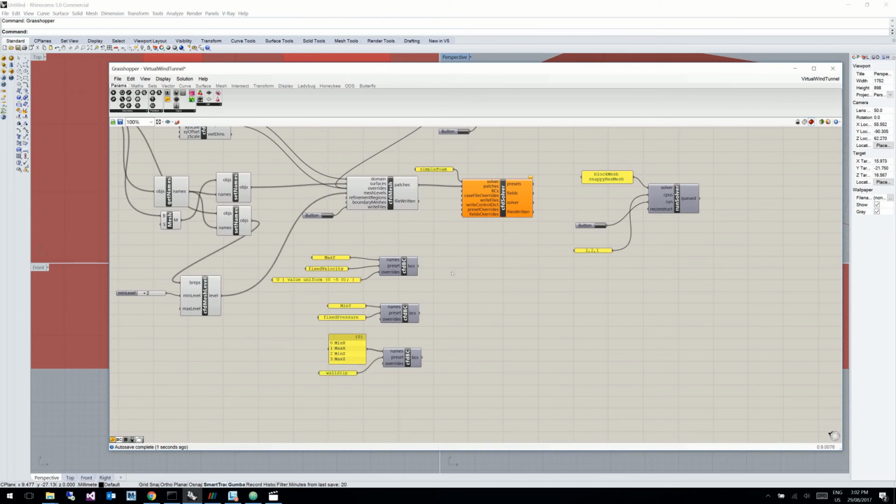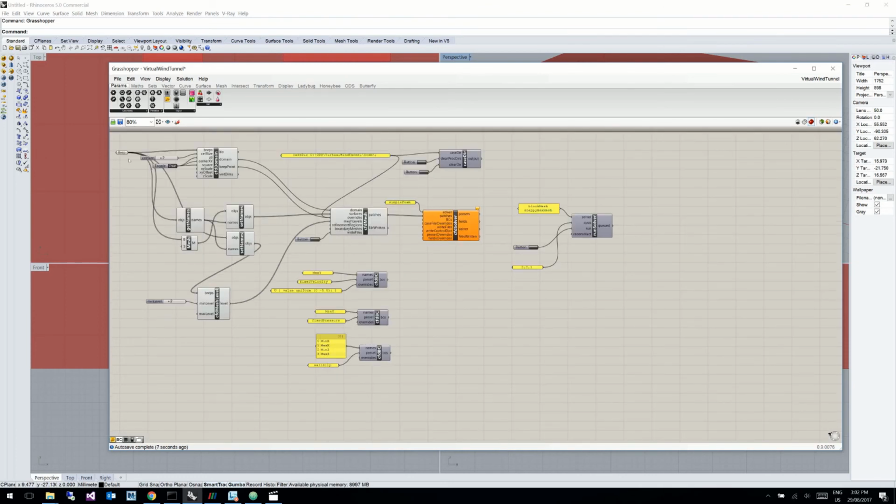Obviously, if you had particular surfaces, buildings, or more complicated geometry, you just grab the names using the getNames component from your original BREPs, and you can feed them into the boundary condition object. So you don't need to manually type every boundary condition name like this. So you can quite quickly construct quite complicated models just using getNames, setNames, and boundary conditions. We'll feed these boundary condition objects into the solver.